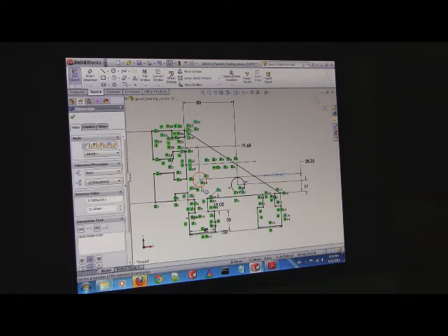Are the radii the same? The way you do that is click both circles with control, then press equal. Now press on the end of that line and hit control and press on the second construction line up a little bit. There has to be a line there. I don't think you have a line on your screen.